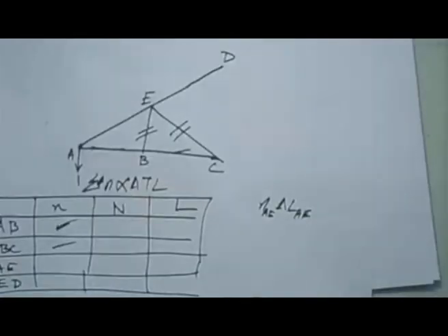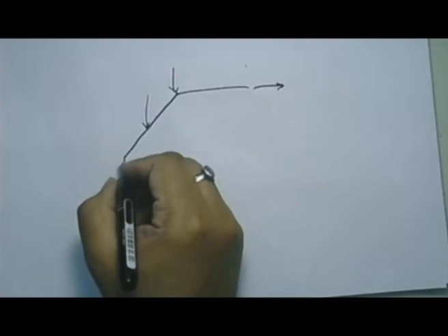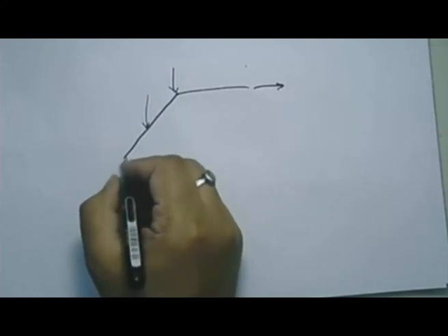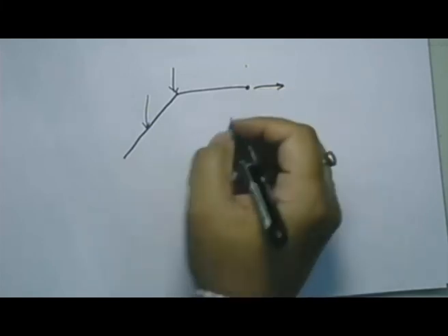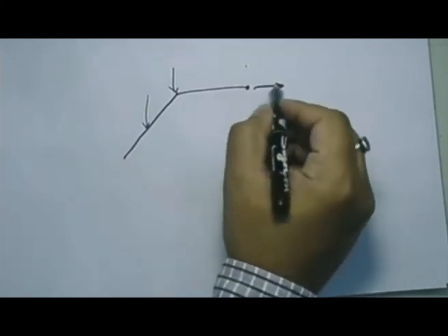So those are the quick discussions on that problem. Now I'll go on to the last assignment problem that I have given. Calculate the horizontal displacement of point C for the frame shown in figure 6 using principle of virtual work and Castigliano's theorem. Now, so you have that frame, and what you are told to do is calculate the horizontal displacement of this joint.